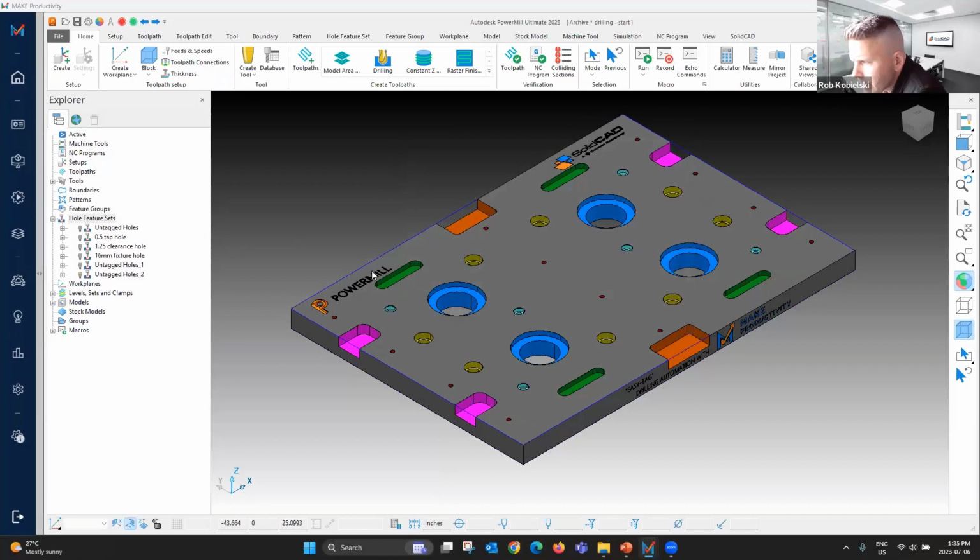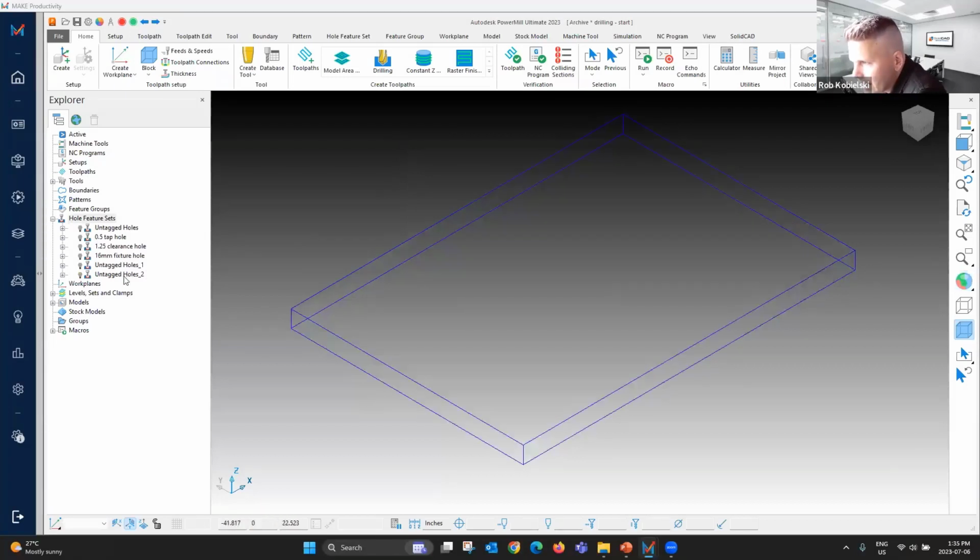Okay, the message simply says, hey, I've recognized some holes like your 1/2-inch tap hole or your fixture holes, but maybe I haven't recognized some, or maybe there were little fragments of holes in which it just gave me some drill tips that I just didn't happen to need in this particular project. This particular set, though, we've purposefully omitted from this portion of the presentation to show you how you can quite easily grab a hole and add it to your standards.